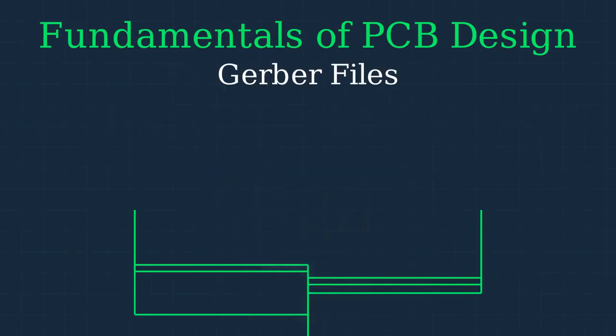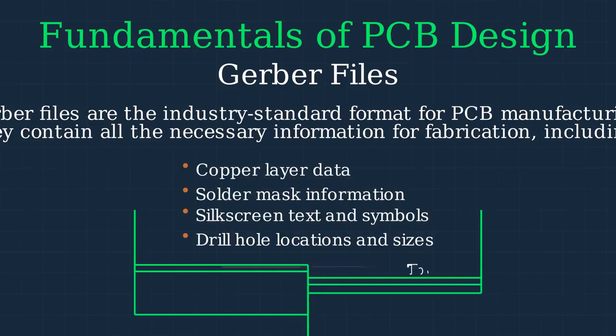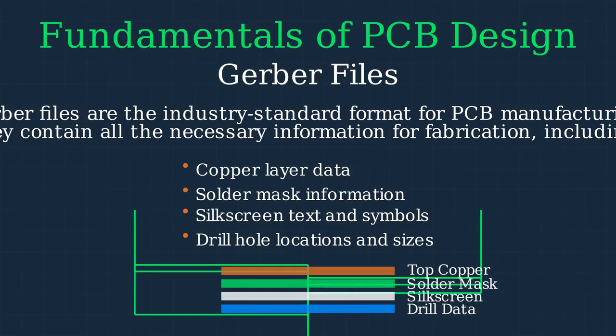The culmination of the design process is the generation of Gerber files, which serve as the blueprint for manufacturing the PCB. These files contain detailed information about each layer of the PCB, including copper traces, solder mask, silk screen, and drill holes.